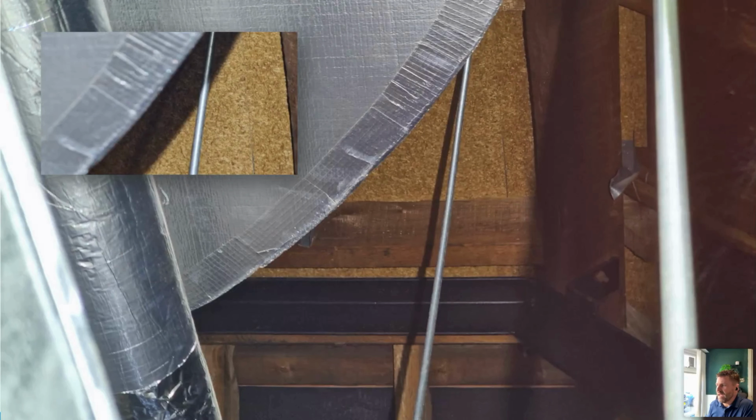So the other kind of timber deck, again, we don't see that often these days. This is chipboard. This is deemed in the HSG 33 health and safety guidance as a fragile deck. So every time we come across this, we should be saying to strip and replace it. When it becomes wet, it becomes very fragile. And if you see it from the underneath, my advice should be not to traffic the roof, because it needs to be stripped.